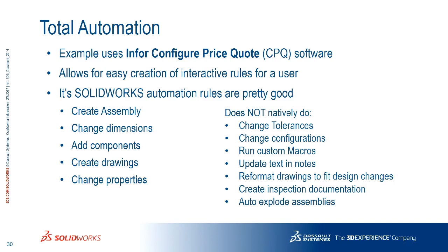It works pretty well. It's when we started to get into wanting to take this to the production environment and really have production level prints that we started to create all these external programs. But the system will actually run those as it goes. You'll just put a call to the external program that you need inside of the system. So I can tell it, I want you to run this custom SolidWorks macro here and do whatever you need to do.